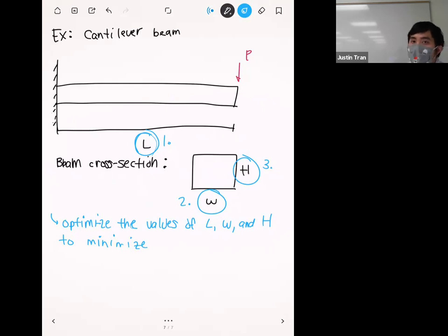Sure. Basically, anything that you have control over in ANSYS, you can have ANSYS optimize over. It would be a little bit different for materials, because these ones, I call them analog variables, because they can take almost any value in a range. For materials, you would have to give it an explicit list of the materials that I can use. And so you can have it optimize over that too.